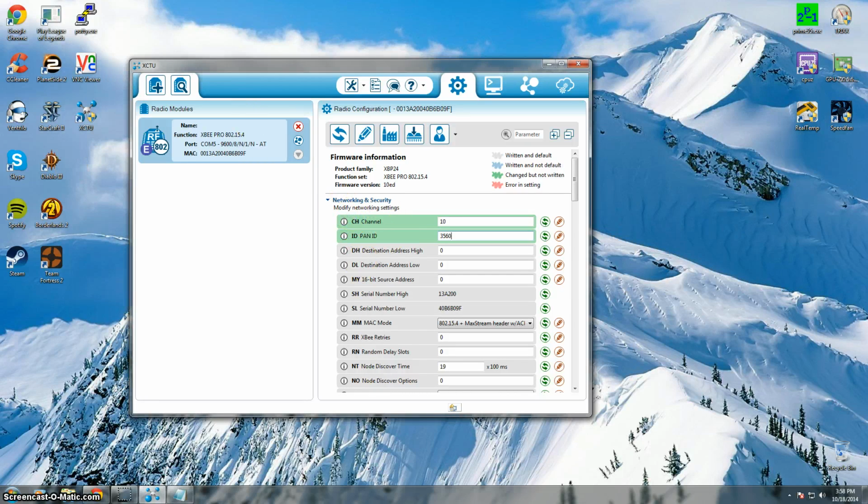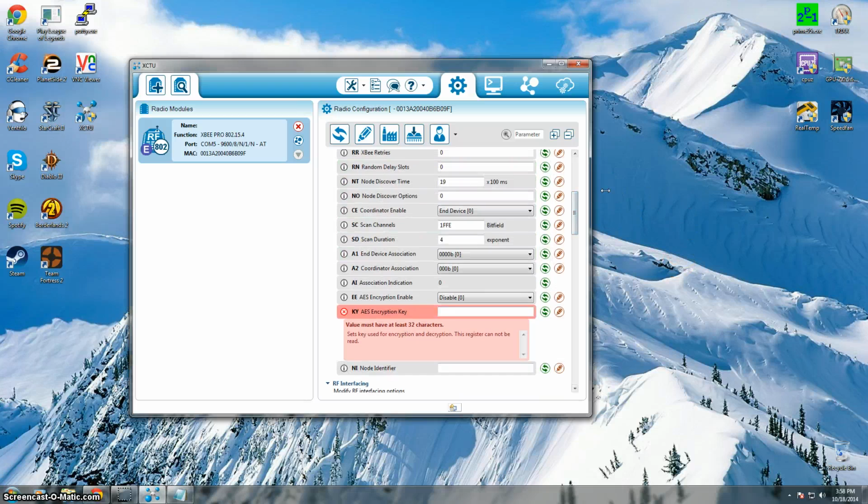Additionally, since the first XBee had a destination low of 5 and a MY address of 0, for the second XBee, we must have a destination address low of 0 and a MY address of 5 so that the two can communicate. Plus, since this is the XBee we will integrate to MATLAB, we will call it MATLAB_XBee.